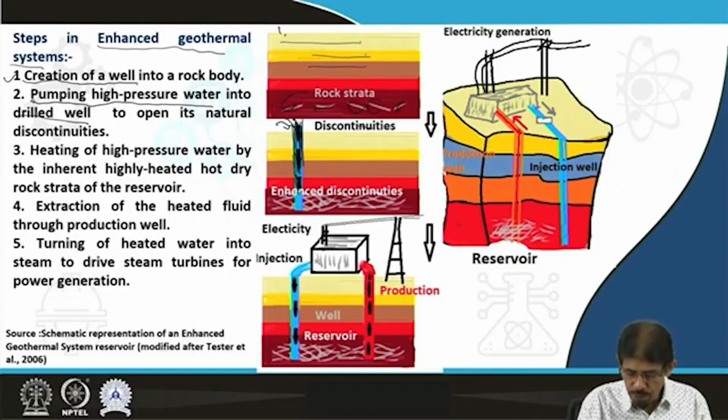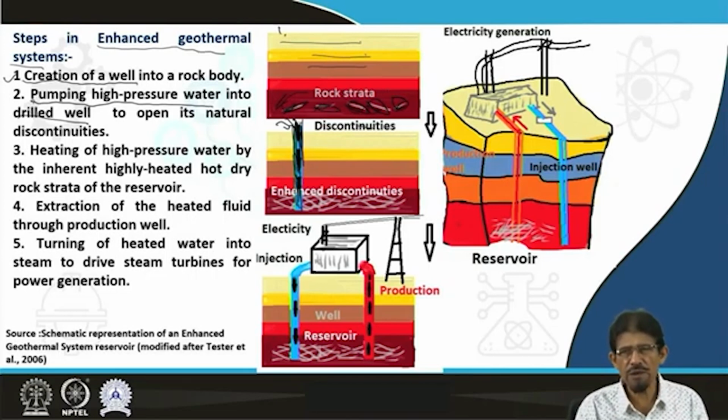Due to injection of water inside the drilled hole, the inherent discontinuities present in the reservoir start opening, with increased aperture, as well as formation of additional fractures due to the injection of water-induced pressure.